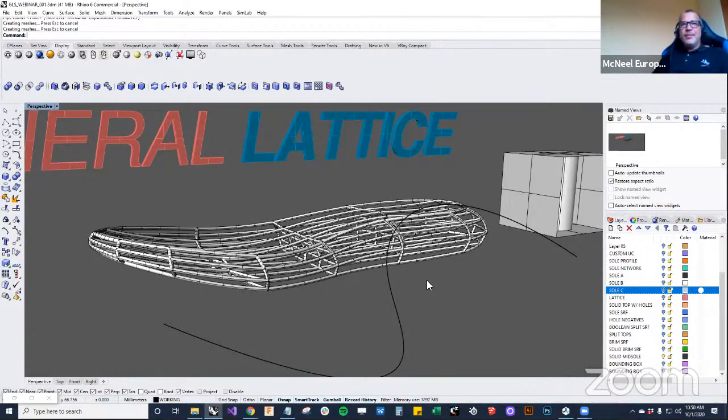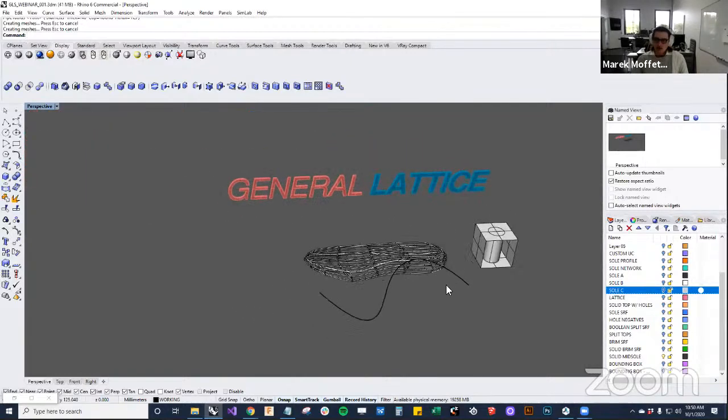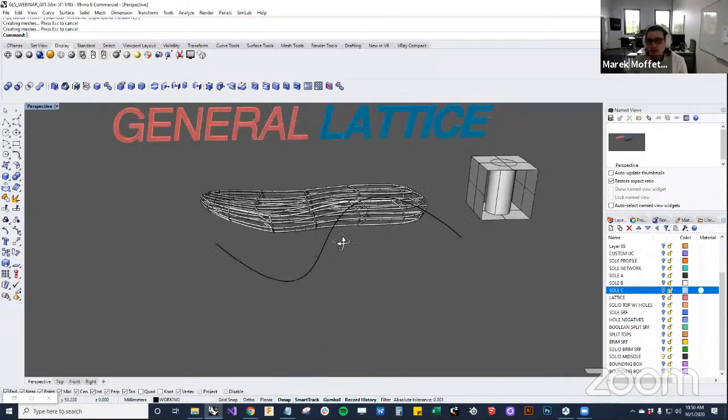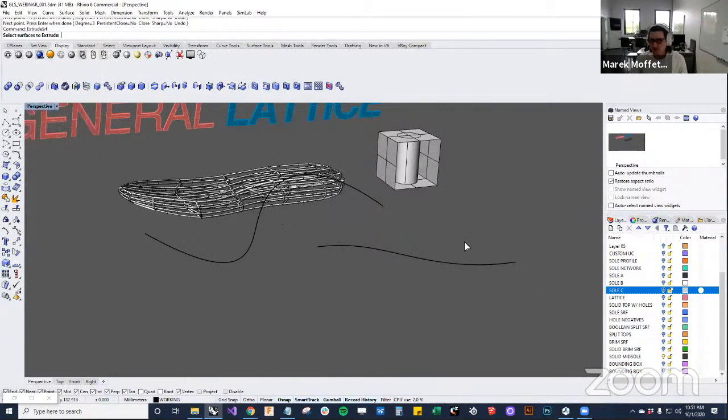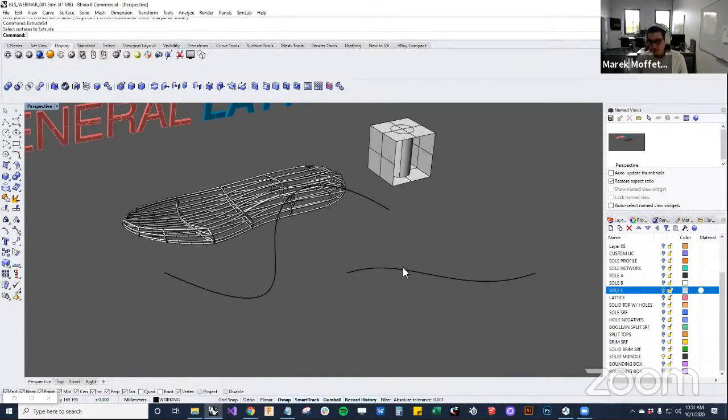Then Arya asks, what's the best way to use Lattice Loft in architectural structures? It's a great question. We have done some exploration of creating wall-like structures and facades and things like that. How you use the tool depends on what you're trying to do with the geometry, but something we've seen that is somewhat common is some sort of wall facade that can be printed on a large FDM machine and is pretty complex. Let me see if I can replicate that really quick. My short answer would be: break your model into surfaces for the areas you want to be latticed, and then work from there.